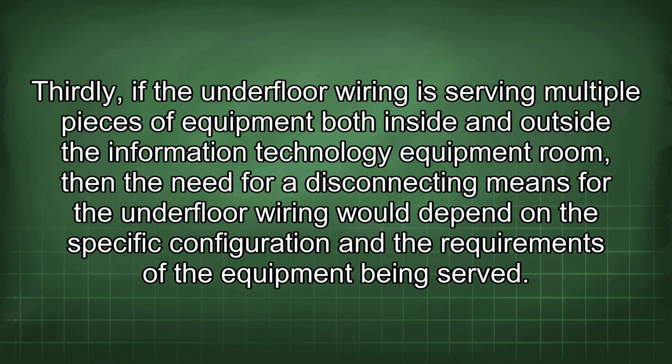Thirdly, if the underfloor wiring is serving multiple pieces of equipment both inside and outside the information technology equipment room, then the need for a disconnecting means for the underfloor wiring would depend on the specific configuration and the requirements of the equipment being served.